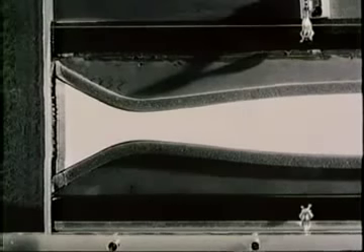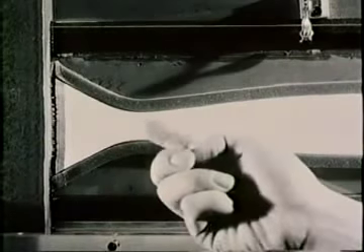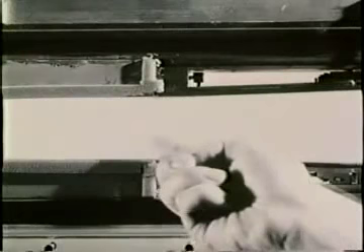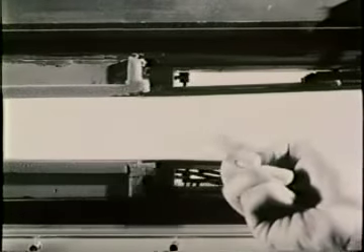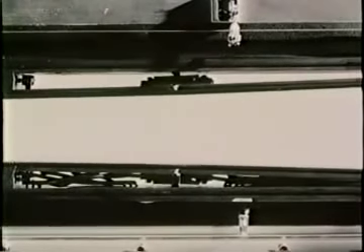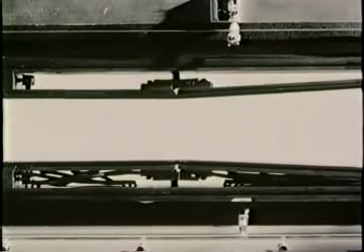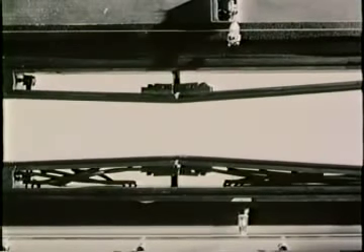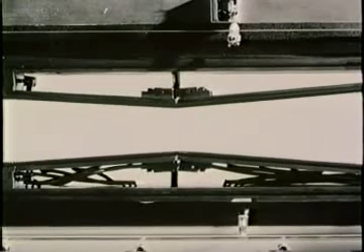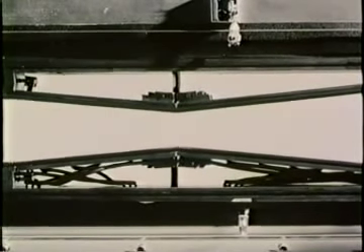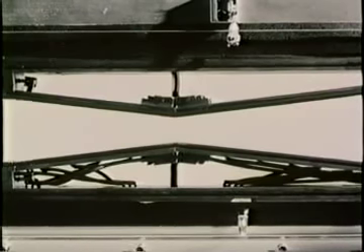We've now changed our channel geometry. First, we have a short symmetrical nozzle designed to give uniform flow at a Mach number of about 2.3 in this test section. Then we have an adjustable second throat, which can be opened or closed to vary the amount of supersonic compression. We now have two means of control over the flow in our channel: the geometry of the second throat and our original control valve. Let's begin by making the second throat smaller than the first one.